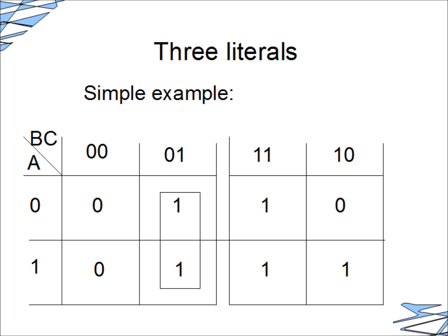Now, we can group the 01 column, but there's something else that's going to come into play now. We can group in powers of 2. So let's just wrap these 4 ones in just one single bundle. Now we are going to obviously discard more minterms and simplify a little bit more. The other thing we're going to be doing is we're going to just group that last one over there, and we just simplified a minterm. Couldn't discard any more, but we already have discarded quite a few. So let's look at the answer.